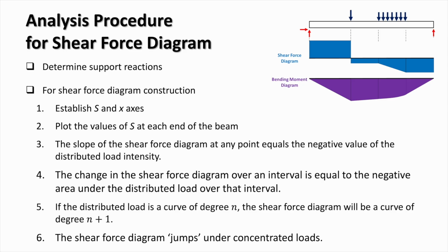Distributed loads, therefore, produce a gradual variation in the shear force diagram, while concentrated loads produce sudden jumps. These relationships also allow us to predict the general shape of the shear force diagram directly from the type of loading applied to the beam.